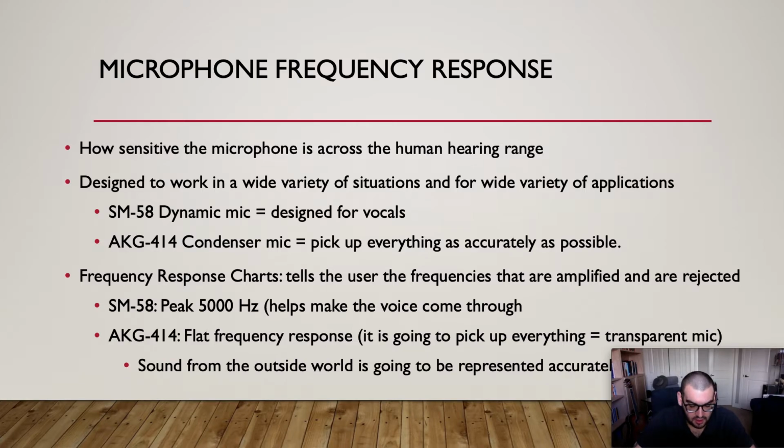All right, let's talk about microphone frequency response. So microphones are designed to work in a wide variety of situations and for a wide variety of applications. Some are designed, like the SM58, which is our dynamic microphone, to work primarily for vocals. And they'll be designed to produce vocal frequencies well and to reject the frequencies that are not usually part of the vocal range.